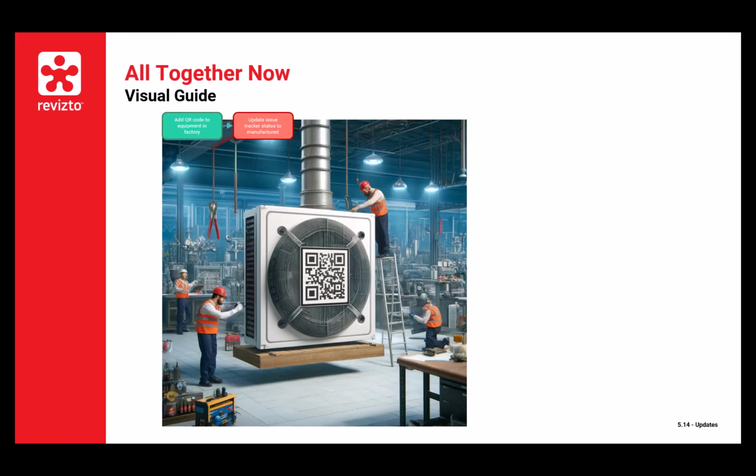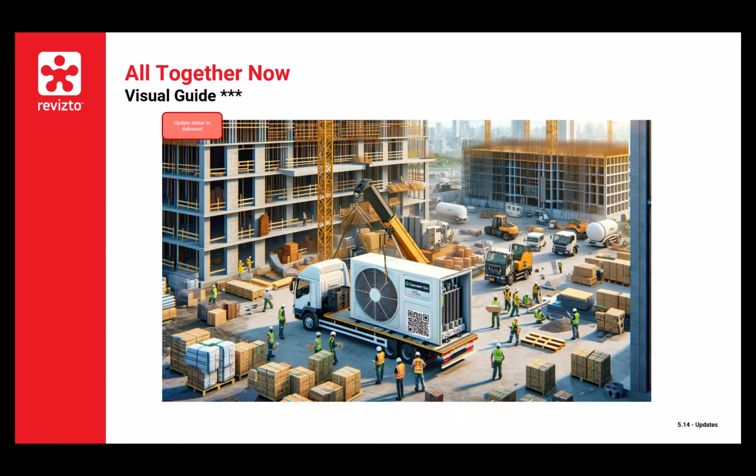Next off, we're going to add those QR codes to the equipment, whether that'll be in the factory, wherever it's being manufactured. We're going to add those QR codes to it. And then we're going to update the issue tracker status to manufactured within the Revizto app. This can also be done via the site app. So you could just grab your mobile, scan this, and then update the status.